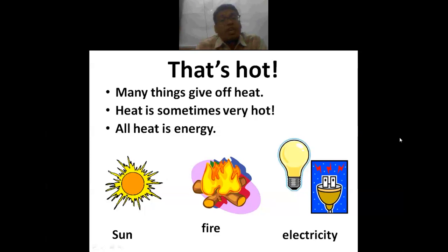So depending on the function and the end product of the process fluid, I call the same heat exchanger a heater, a cooler, a condenser, an evaporator, a boiler or a reboiler. They are nothing but heat exchangers with slight modifications depending on the requirement. So this is what is happening in our industries.